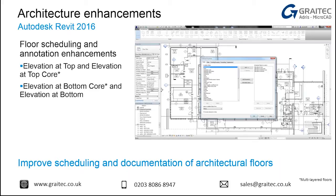The ability to schedule floors has always been there, but one of the things we've never been able to do is pull in information regarding the floors. So we've now got the ability to pull in the top elevation, the core elevation, so what the levels are within our floor, so we can understand where our floor actually sits within our projects. It might sometimes be offset from a level. We get much better information within our schedules regarding that.